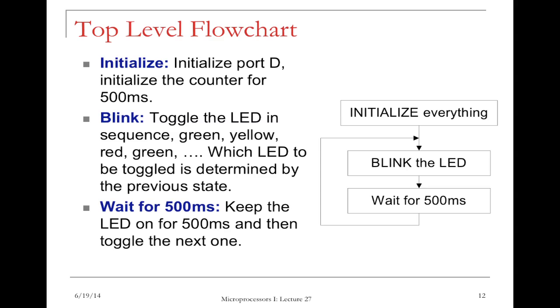Also, maybe at the very beginning you want all the 3 LEDs to be off. That means not only do you need to tell the microcontroller that port D is an output, you also want to output low voltage or logic 0 to the pins so that these LEDs are all off. Make sense? Yes or no? Yes? Okay. So that's what we mean by initialize port D.